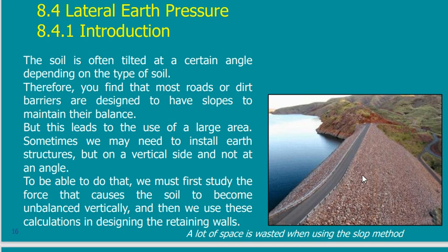This is a shape of a retaining structure, this is a dam. A dam is something for retaining horizontal forces, something similar to the High Dam in Egypt. On one side, water will rise maybe until it reaches near the top of this dam, and on the other side it is dry. So there is horizontal force from one side, and this horizontal force is coming from water, similar to the horizontal force that will be coming from soil. The concept is that we have horizontal force.